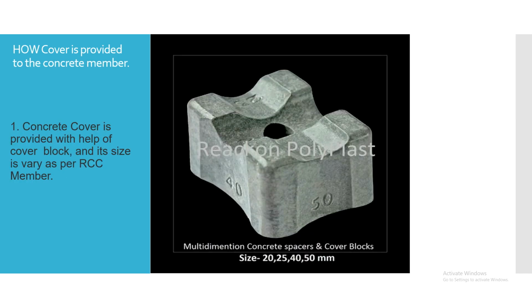Next, how it is provided. Cover काय असतो आपण बघितलं, cover का provide करतात बघितलं, that is a concrete cover, okay. And the next part is how it is provided. Cover is provided with the help of this cover block. So cover block म्हणजे काय? You can see on your screen, this is your cover block, okay. If you face upright it will be 40 mm, if you face like this 25 mm, if you like this 50 mm, okay.